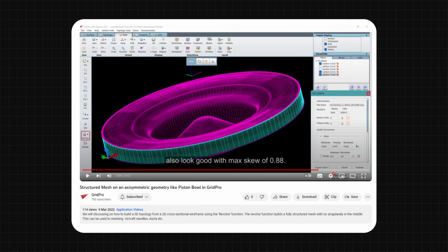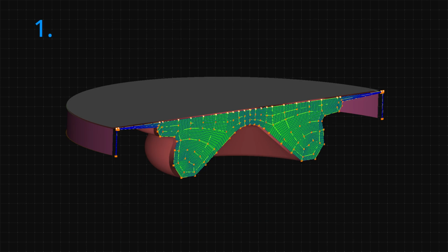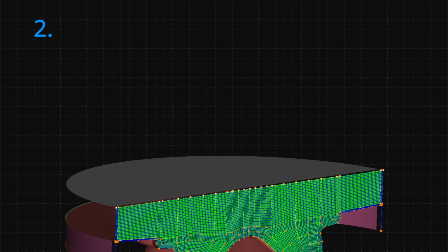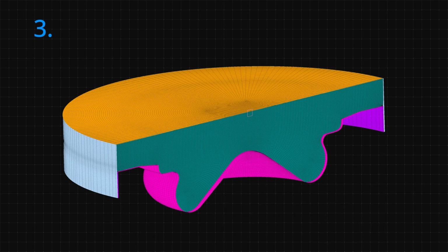There are several ways in which the mesh movement can be automated. 1. By moving the respective surfaces and corners in the topology and changing the density based on the change in length. 2. By moving the surfaces in the topology but allowing the density and hence total cell count to remain constant. 3. By extruding the faces of the generated grid. No modification in the topology.